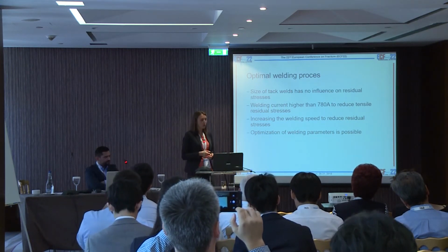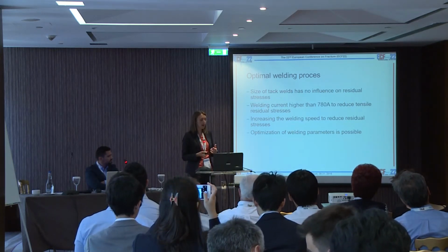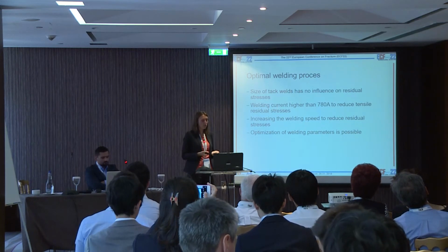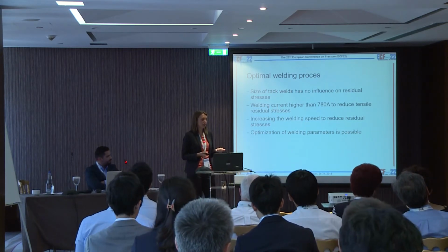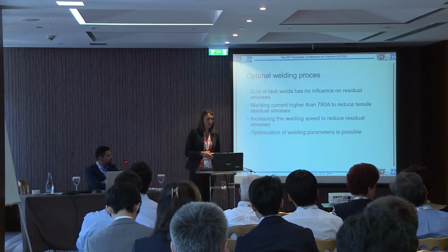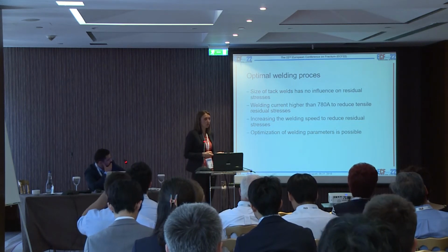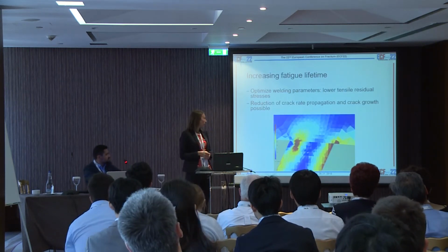The size of the tack welds has no influence. We have to make sure that the welding current is higher than that from our reference model, and the welding speed is increased in the way that it is possible. This leads to an optimized welding process, which leads to smaller tensile residual stresses.